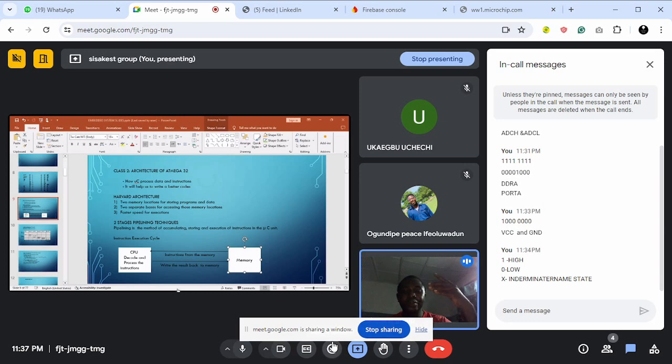So in von Neumann architecture, you have the same 8 wires that connect your data memory to your CPU. It's the same 8 wires that connect your CPU to your program memory. So when you are in the fetching stage, fetching instructions, what to be done from the program memory, you cannot be writing to the data memory at the same time.